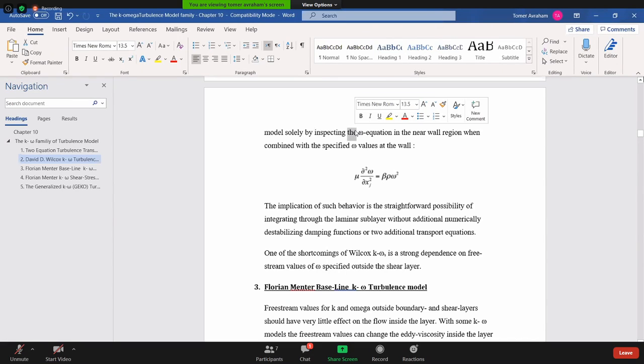When we get to a level of mesh which is refined enough, it switches to large eddy simulation, and then when it's not refined enough, it switches back to Reynolds-averaged Navier-Stokes in one equation, like the Spalart-Allmaras equation, or the k-omega equation, in the case of Fluent. But they suffer from a lot of problems.